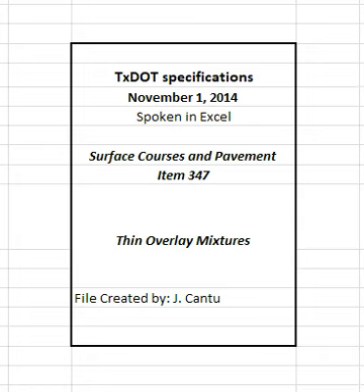4.9.2.2 Production Sampling. 4.9.2.2.1 Mixture Sampling. Obtain hot mix samples from trucks at the plant in accordance with Tex-222-F. The sampler will split each sample into 3 equal portions in accordance with Tex-200-F and label these portions as contractor, engineer, and referee. The engineer will perform or witness the sample splitting and take immediate possession of the samples labeled engineer and referee. The engineer will maintain the custody of the samples labeled engineer and referee until the department's testing is completed.